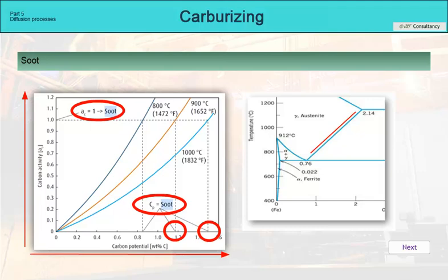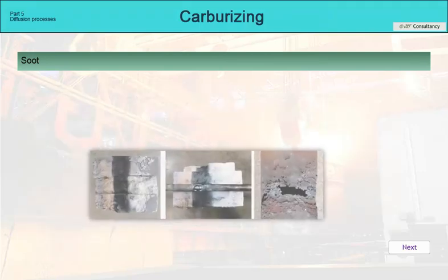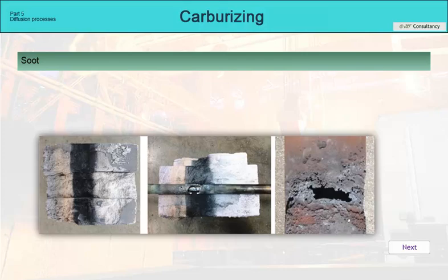Not only are the components themselves at risk from excessive carbon content in the furnace, this also applies to the carburizing equipment itself. Excessive carbon exclusion in the form of soot significantly worsens the service life of the lining. The more carbon the lining absorbs, the more it loses its thermal properties, even becoming electrically conductive. As a result, damage can occur to the metal housings or the probe shell, since carbon supersaturation can lead to the eutectic point being reached and the material melting.